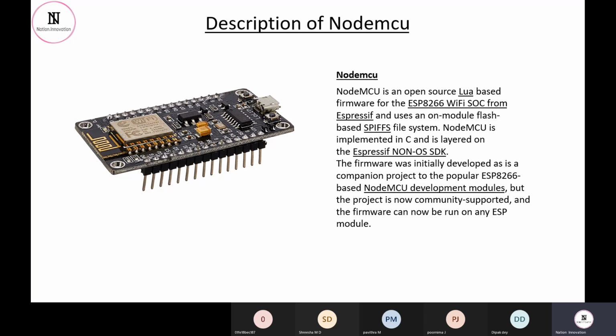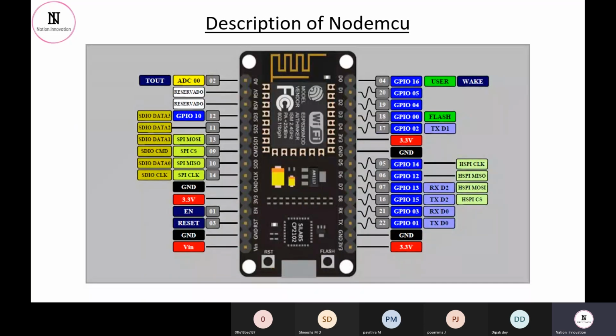Second good feature with the Arduino Node MCU is that it can be put into a deep sleep mode to save power. Suppose there are some devices which require sending some data on a periodic basis, like after 4 hours, after 2 hours, after 3 hours. In that case, if we have a clock system around it, then we can put this Node MCU into deep sleep mode and save power. If we compare continuous working with deep sleep mode, how much lifetime we can expect changes drastically.